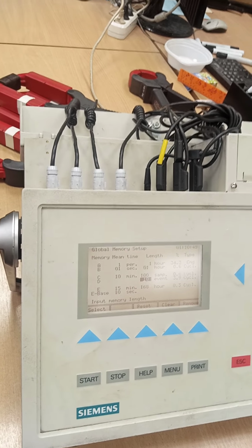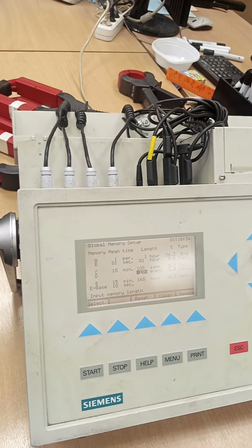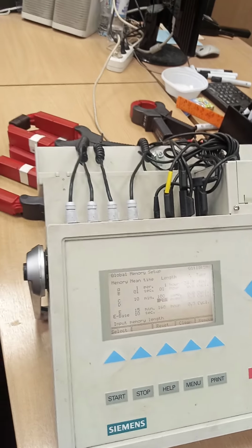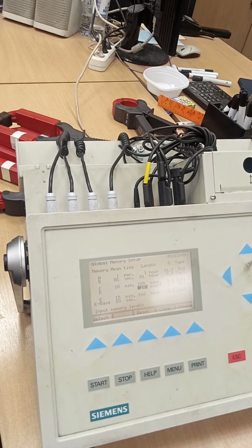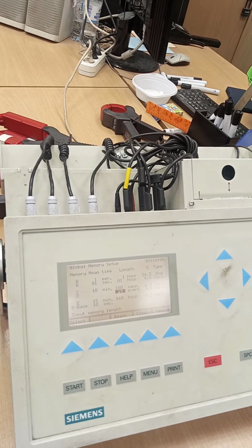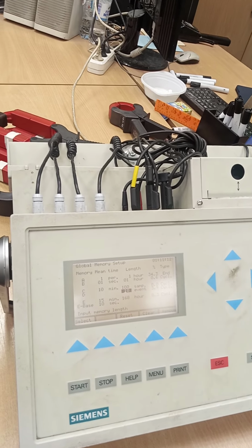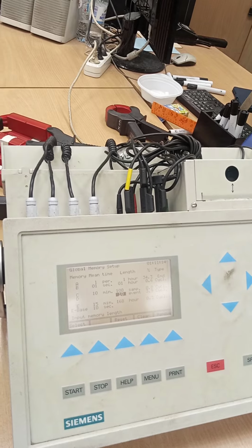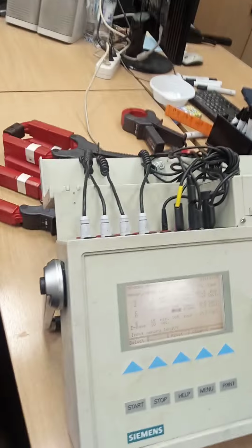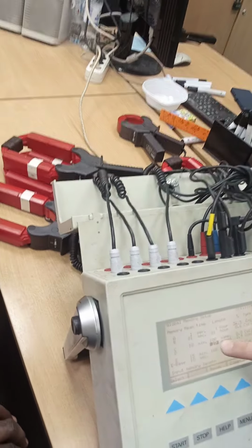It's once again a very big volume of data, and they are not necessary. We do not need waveforms for 1 hour. We need to see waveform if some event occurs, like disconnection, like voltage dip, like some impulse. So it is set like a number of events. For example, 10 events.